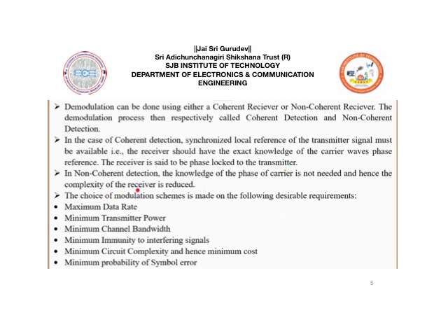Coming to non-coherent detection, here the knowledge of the carrier's phase is not shared with the receiver. The knowledge of the phase of the carrier is not needed at all, and the receiver will not know any information about the phase of the carrier. It is not shared by the transmitter with the receiver. This is one of the advantages, which incurs less complexity in the receiver.